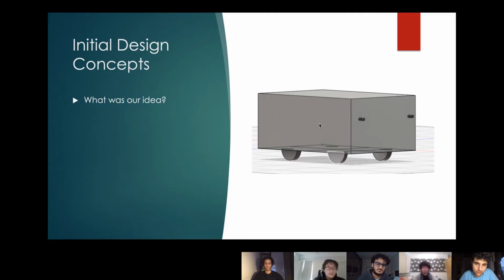The initial idea we thought of was to use springs. It works by having two springs on the front of our car. Those springs would have two purposes. The first purpose is to slow the car down, which we decided to keep on our final design. The second one was that it would create enough of a reaction force so that when it hits the wall, it will rebound and land at the bullseye. However, the plan was abandoned because the system is too hard to control. This is because if the springs produce too much force, then large oscillations may occur and cause the vehicle to move unpredictably.